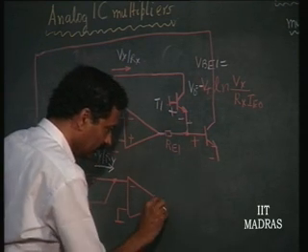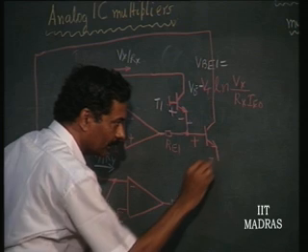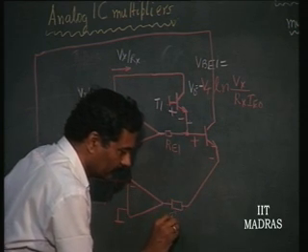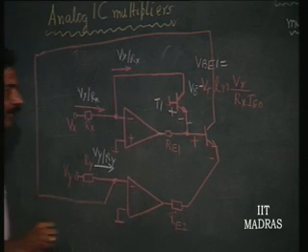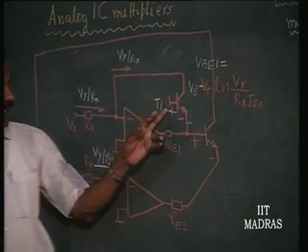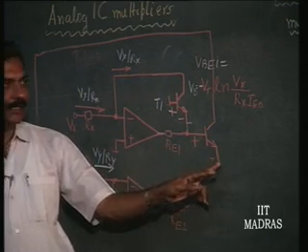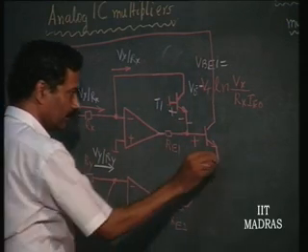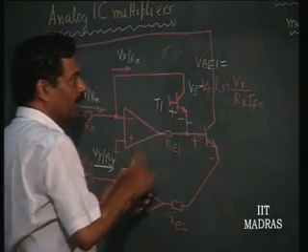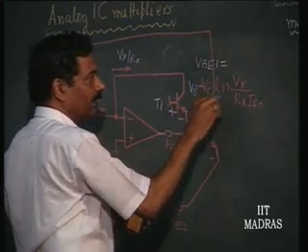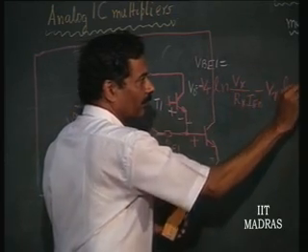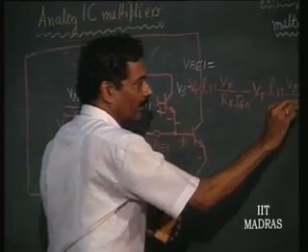So, once again I will put Re2, so that there is negative feedback for this. Is this clear? So, ultimately now we are getting a voltage here at this point, which is nothing but this point output, let us say we are taking, that will be nothing but minus Vt log Vx by Rx Ie naught, minus Vt log Vy by Ry Ie naught.